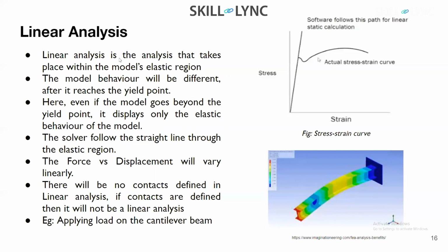Meaning most components which have elastic behavior, where upon removal of load your component comes back to its original shape, the analysis can be termed as linear. If I plot a force versus displacement graph and it is linear, I can also say that it's linear. Also, when I don't have any contact between bodies, I can take that as linear analysis.